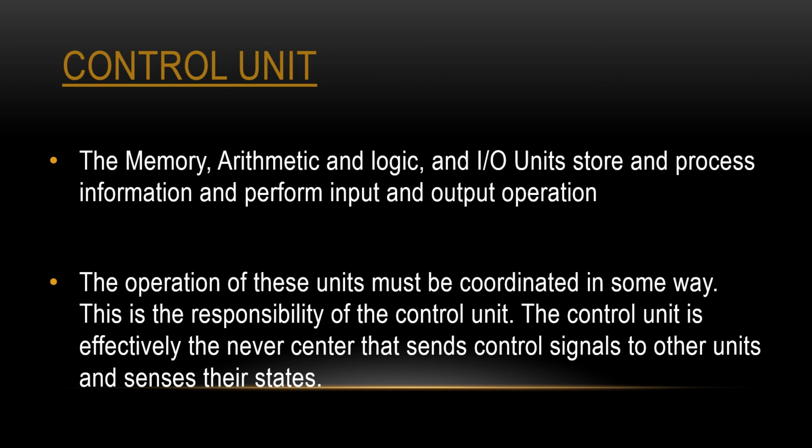The control circuits are responsible for generating the timing signals. When you generate the timing signals, then we can perform the read operation or write operation. So that will govern the transfers and determine when the action is to take place. Again, some handshake signals are also used when we are performing input-output.